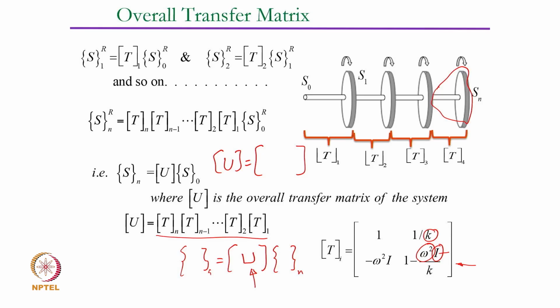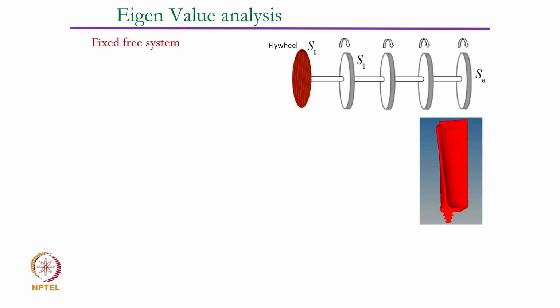Or formulate even. What we do is, let's look at one simple practical system, like the same gearbox is connected to a huge flywheel on one side, let's say, as an example. In the case of a cantilever, it gets routed to the disc, so one end of it is fixed, provided that you model each of these segments as individual, having its own torsional stiffness and inertia. But this is another example of the gearbox that we saw. Suppose one end is fixed to a big flywheel and then the other end is free.